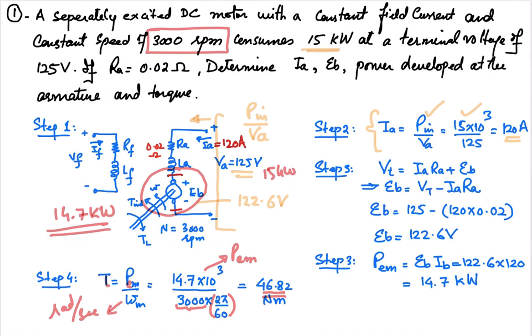With the passage of time during this tutorial, you will see that back EMF plays a very important role in the operation of the machine. As we discussed in the theory lecture, back EMF is equal to K times flux into omega. It depends upon the flux and the speed, and can also be written as KB into IF into omega. It can be controlled by controlling the field current IF in this circuit and the speed of the machine. Both affect this back EMF.